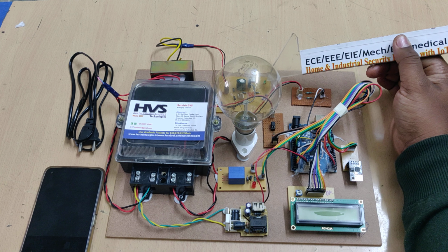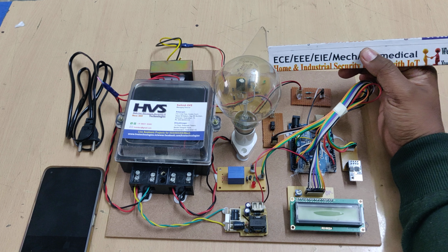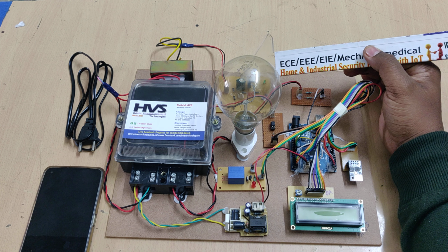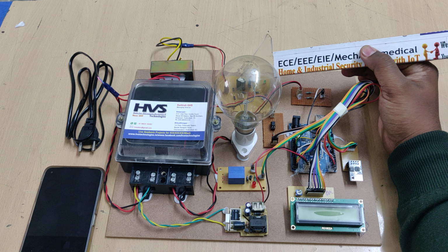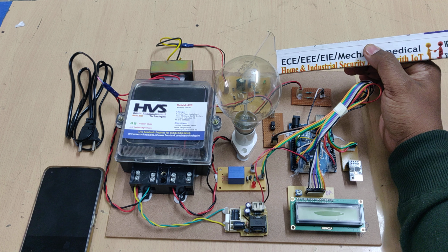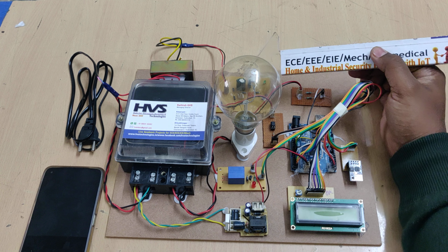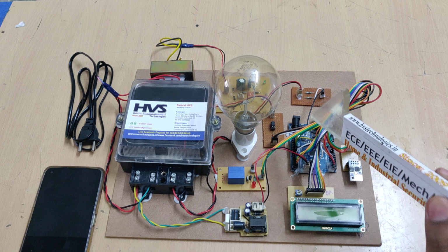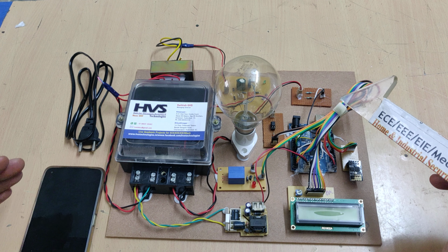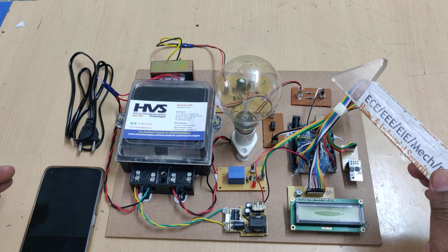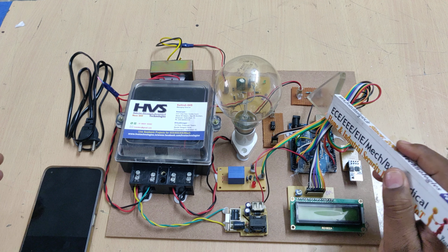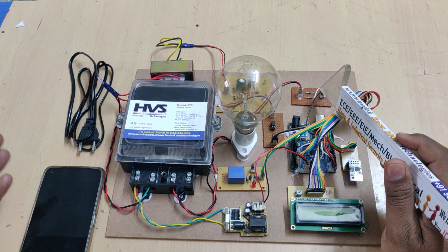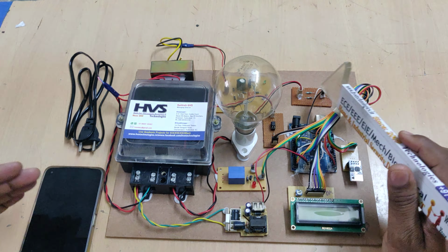With the help of this regulated power supply board, we convert that AC to pulsating DC, and the pulses are removed with the help of this capacitor. After that we get pure DC without any ripples, at around 12 volts. The controller can't measure 12 volts, so again we need to do a potential divider voltage conversion. Here we are using 10:1. For example, if the controller gets 1 volt after this potential divider, it will take it as 11 volts, as we are using the 10:1 ratio.